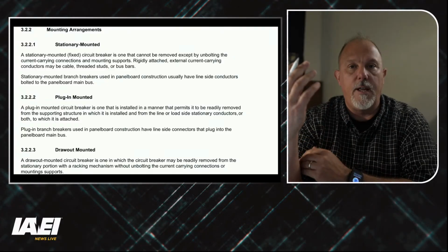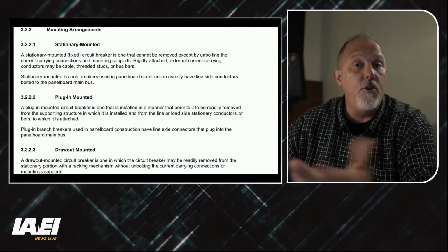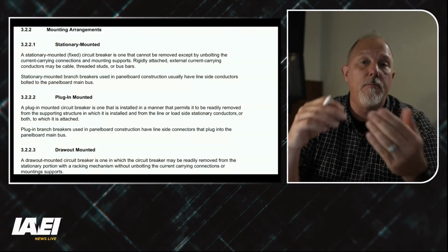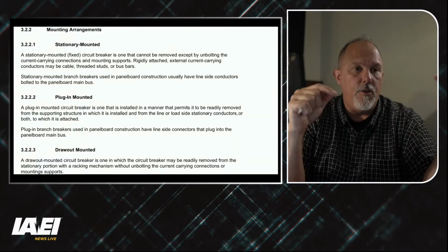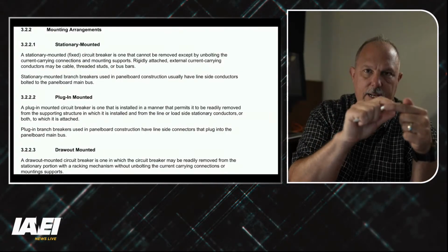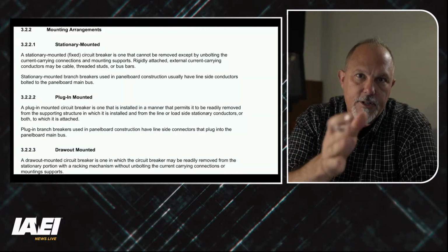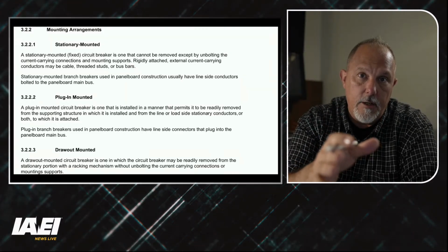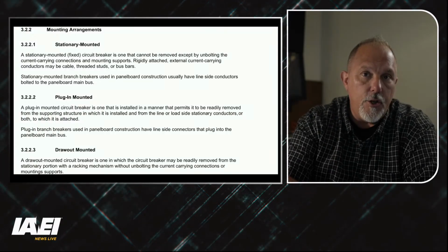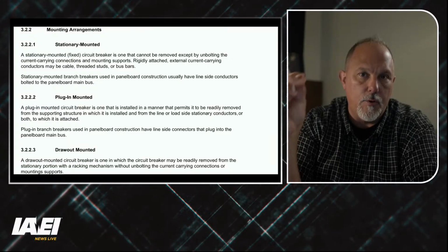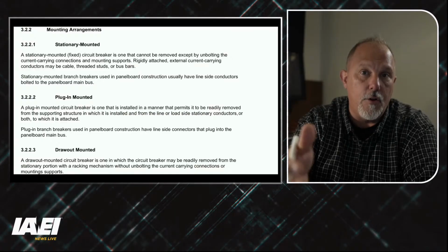It's important to understand the breaker has to mate with the bus that it's being mounted to. But you may also have a cable in, cable out, right? So you may have a circuit breaker where you land a cable in on one side and you put the cable on the other side, and you have two terminations. So understanding your application, working with a manufacturer of your choice, you can identify the appropriate termination points or methods for your application.